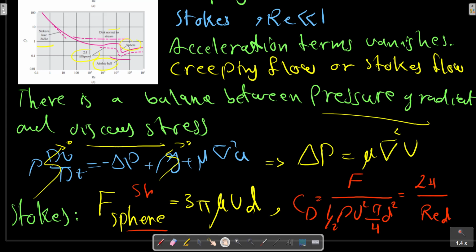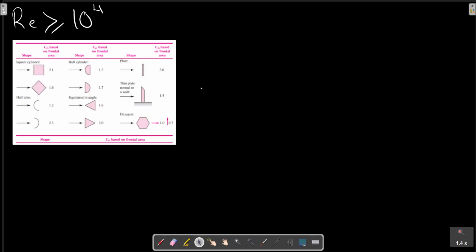There are also tables that give a few data on drag based on the frontal area of two-dimensional bodies of various cross sections at the Reynolds number. For the sharp edge bodies, let me provide the tables related to the drag coefficient for a square cylinder.